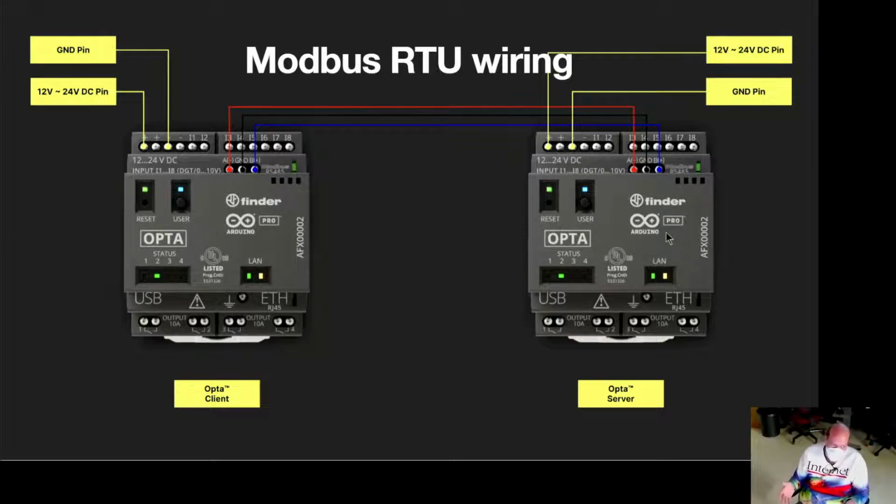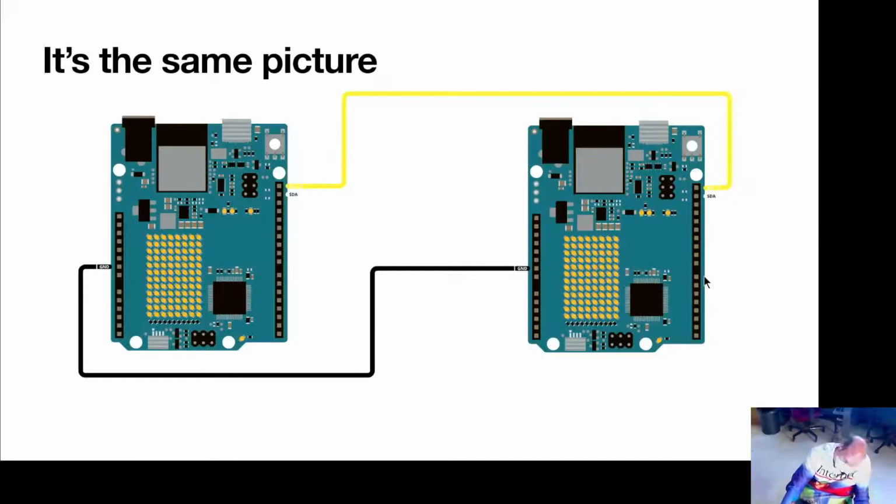So if you're connecting devices with Modbus RTU, you connect the corresponding pins. So the center pin is ground, the pin on the left is A-, and the pin on the right is B+. And you connect A- to A- and B+ to B+. This is unlike a UART serial where you connect TX and RX. But part of the reason, or the helpful reason that's notable here, is that you can have a third device that you also connect A- to A-, and B+ to B+, or fourth, or 20th.